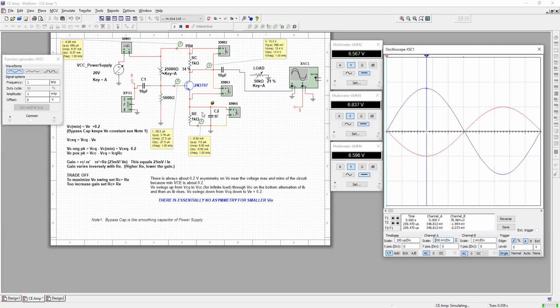So now we see that the capacitor here is essential to increasing our gain because it basically takes the emitter resistor out of the circuit for the AC fluctuation. Okay. Now let's understand the third capacitor that's connected to our load. Right now it's connected to an infinite load, which is the oscilloscope. So this would be the no load operation. We've been looking at the output form all along. We're going to study the impact of this capacitor.